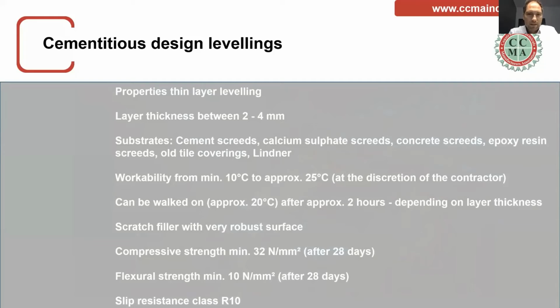There is a second kind of design leveling, which will be troweled directly on the floor by doing some kind of scratching technique. By using this technique, we have a layer thickness between 2 to maximum 4 millimeters. That is very good for renovations, very good for refurbishment. Like the other product, you can do it on cement screeds, calcium sulfate screeds, on concrete slabs, old tile coverings as well, and of course on Lindner floors.